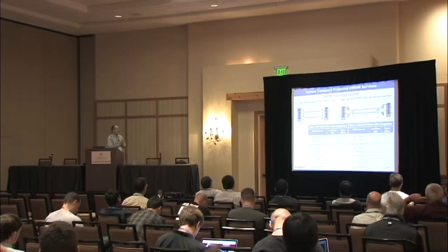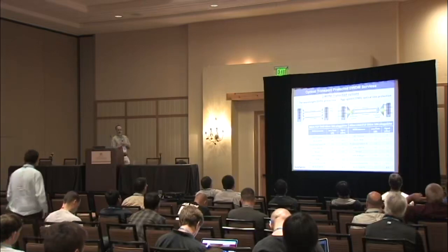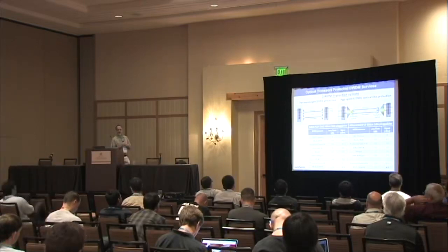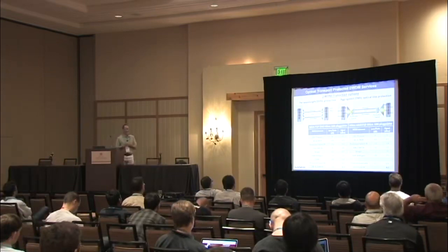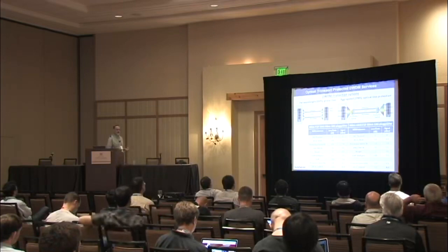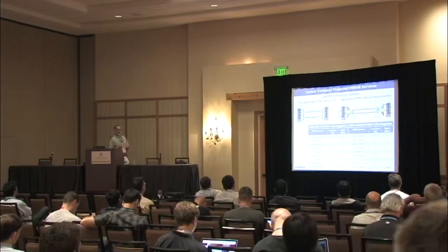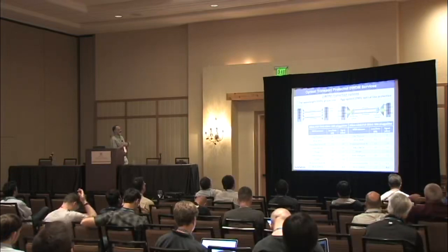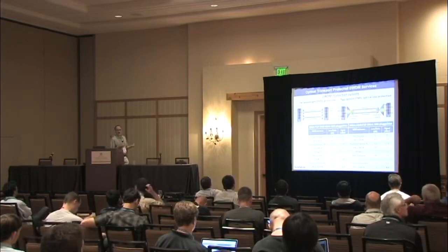Now I wanted to touch on how to implement protection and, again, optical design calculations. The left one is optical per wavelength, so optical channel protection, that's done by doubling your transponder, so doing transponder redundancy within the transponder or full hardware redundancy. The calculation is exactly the same as for a simple channel.